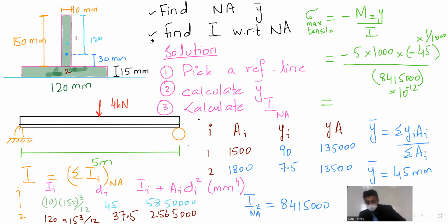There will be a lot of shearing between the layers. And we will see that the neutral axis line will have the maximum shearing stress. When we incorporate that, then probably we will get more results out of this. But right now, as we speak, I'm specifically saying bending stress.